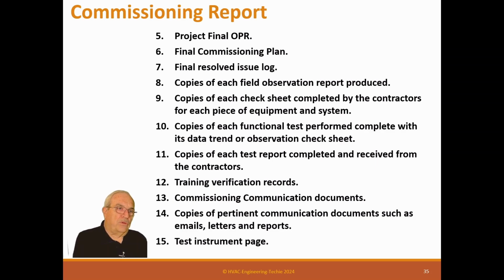Now, if you need something really special, the contractor is supposed to provide those, but as far as a standard volume meter, standard amp meters, standard pressure instruments, standard temperature instruments, standard humidity instruments, standard CO2 instruments, you should have those. And the reason is the contractors on site have those instruments. If it's involved in their craft, they're probably not calibrated. And that's a big issue. The owner has them. They're definitely not calibrated, which is really irritating. But so you need to have those instruments so you can say they're definitely calibrated, and this proves that the system worked correctly.